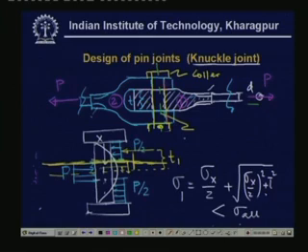If the material is a ductile material, then we have to use the other failure criterion, namely the maximum shear stress.